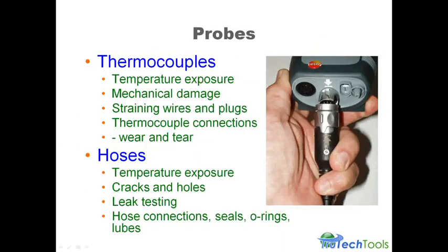Probes and thermocouples: again, you don't want to expose those to excessive temperature. You've got to make sure the thermocouple is centered in the probe. Make sure there's no mechanical damage. You don't want to strain the cord or the wires. You don't want to carry the thing around by the probe; make sure you're carrying it by the analyzer body. Check your hoses periodically to make sure there are no cracks or holes. You can leak test the analyzer.